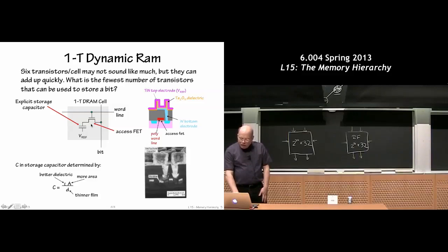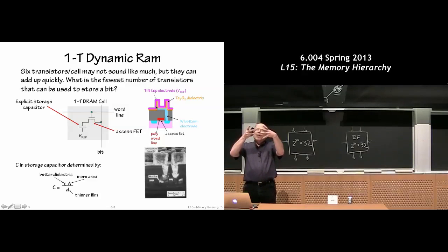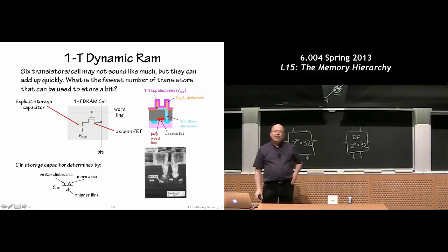And so you start getting very strange looking structures. I don't know how well you can see this in the slide. This sort of looks like a rotten tooth, right? What it really is is a cylinder where there's an internal metal cylinder that's been covered by a dielectric insulator, and then there's another metal plate that's gone on top of that. So I've made this cute little dielectric metal sandwich, which is basically a very small capacitor.